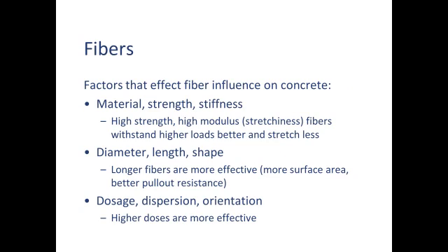So when you buy fibers, the fiber manufacturers have tailored the length to diameter ratios for you. You don't have to think about that. All you have to do is look at lengths. The longer the fiber, the better it's going to be, because most fibers fail from pullout, where the fiber physically just pulls out of the concrete. It's pretty rare to actually see fibers failing, at least early on. Long term, that's a possibility, but generally your short-term failure is fiber pullout. So your longer fibers are going to give you better early green strengths than long term.